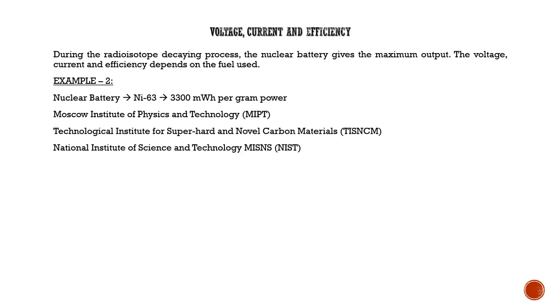I think most of us have heard about the nuclear diamond battery. So diamond is used as a nuclear fuel. Here, the PIN configuration structure or the diamond semiconductor boosts the voltage and increases the power output. For a normal nuclear battery, the average open circuit voltage and the short circuit current are 1.02 volts and 1.27 microamperes, respectively. So the maximum output power of 0.93 microwatts can be obtained at